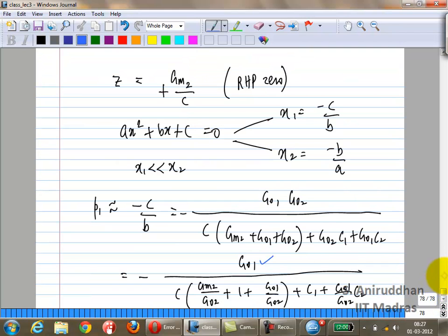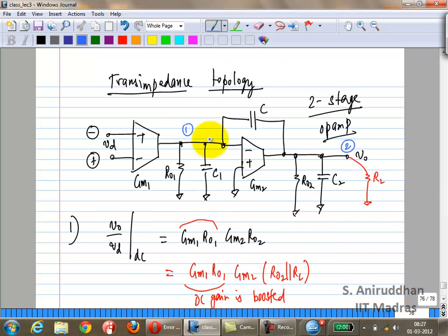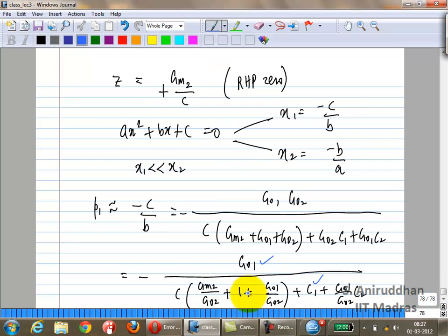What do you see? You're expecting to see the total capacitance at that node, right? You see C1. C1 definitely appears there. What else do you see? It is the Miller multiplied capacitance. So you see something like 1 plus A times C kind of term. Correct? And you have studied the Miller effect in the previous course, right?